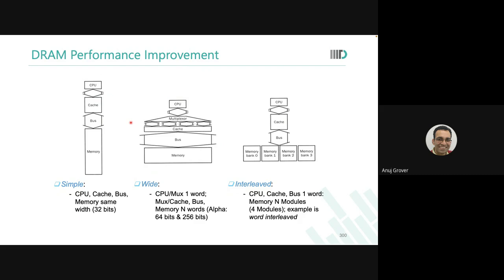Typically, interleaved access is used, why? Because simple access is very slow. Simple access won't work. But wide access is also very difficult. However, Madhav, when you ask that if I have on-chip DRAM, I have no shortage of bandwidth, then one could still think of wide access, but there you will start losing a lot of area. So one has to be careful.